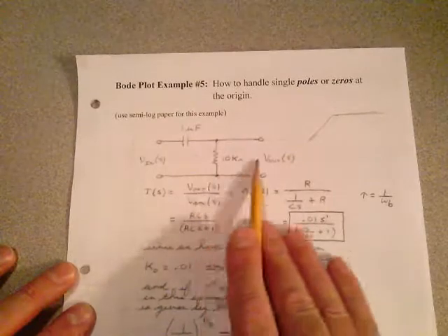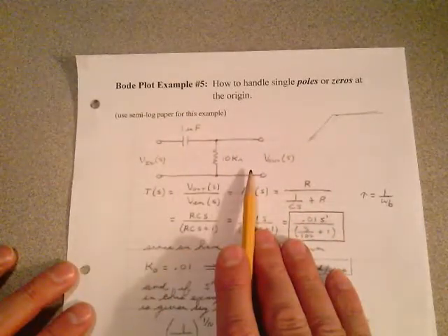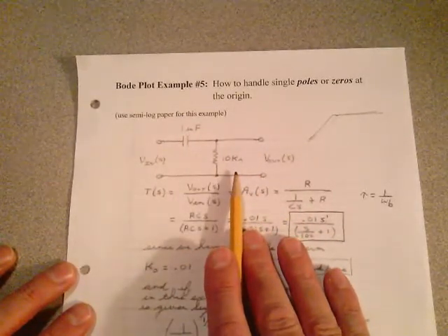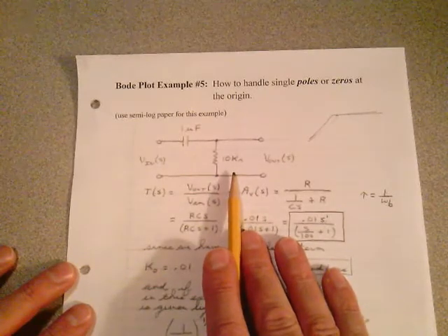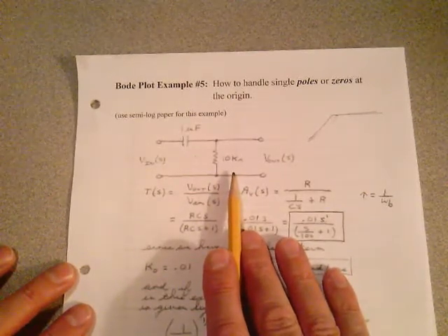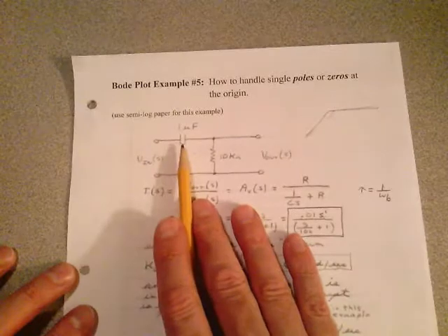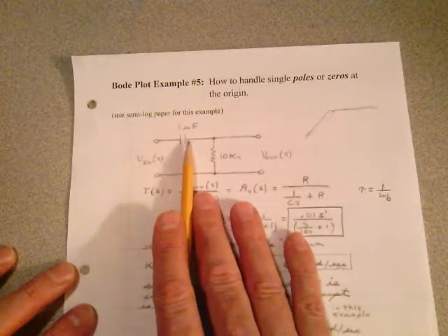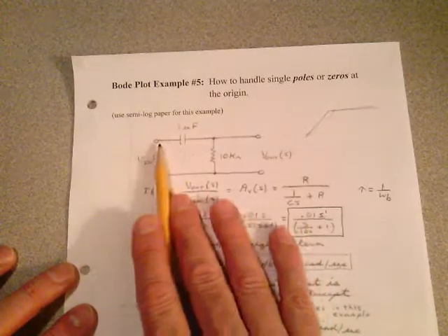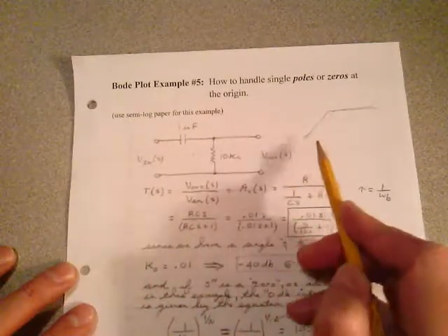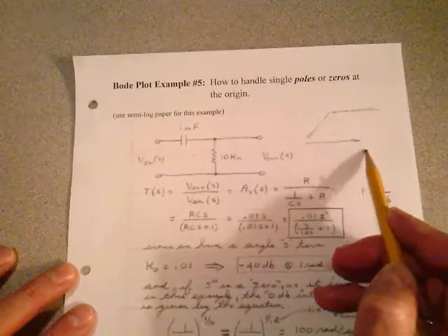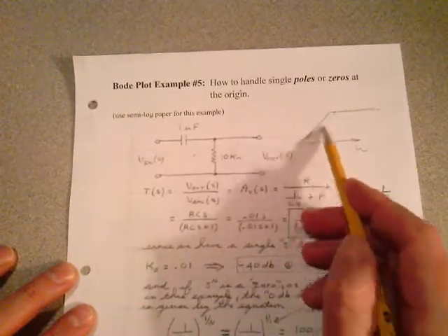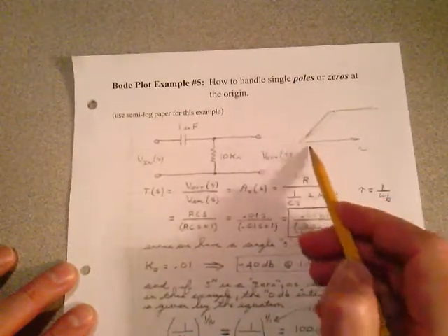Now, before we go through and look at the Bode plot for that transfer function, let's take a look at this circuit and analyze it from a low and high frequency standpoint. At the real low frequencies, and what's the lowest frequency? Well, it's DC. That looks like an open circuit because DC can't go through these ideal capacitors. So it blocks the signal. At the low frequencies down here, this is omega, you're killing the signal. The signals can't get through.